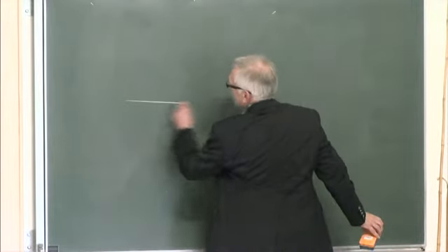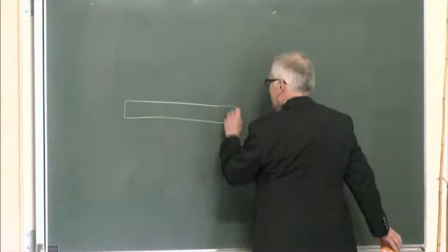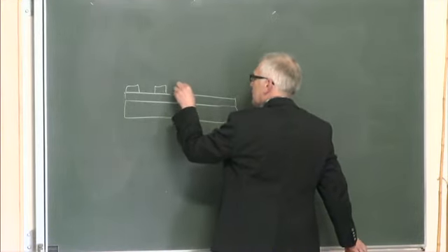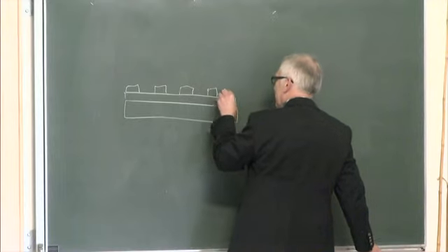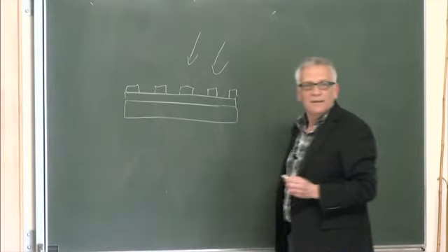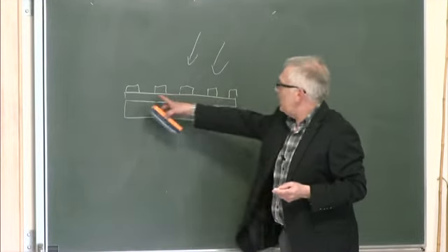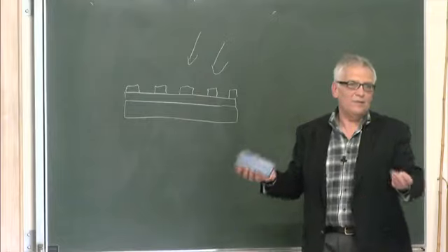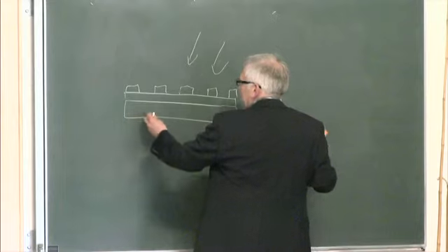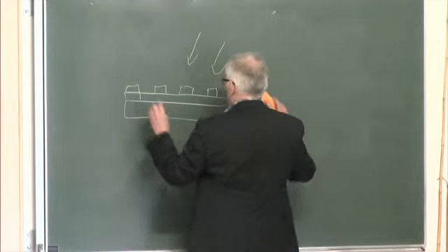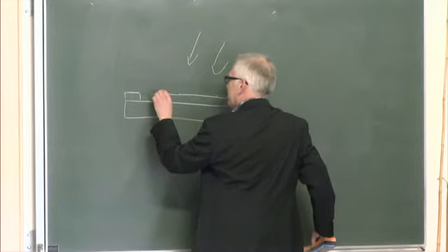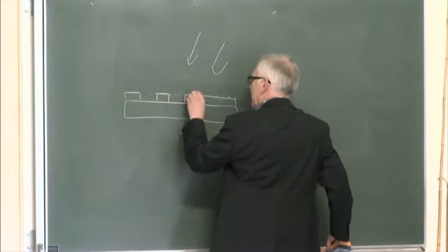So you take the plastic, photoresist, you put on a mask. This is just a simplification, but you put on a mask and then you expose it to UV light. Parts that get exposed then become essentially soft, and you can wash them out. It's like developing a film or something. So then you develop it, and these parts disappear, and what you're left with on the surface then is a grating.